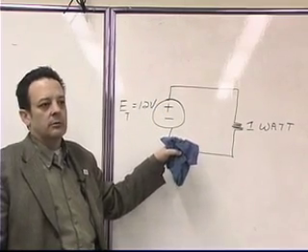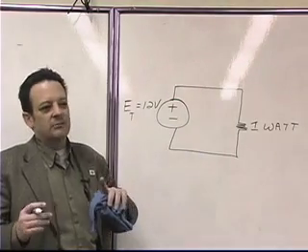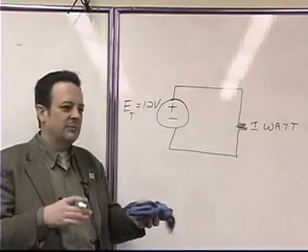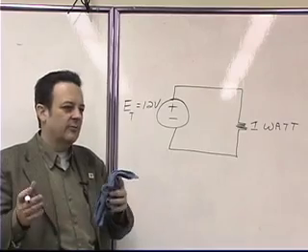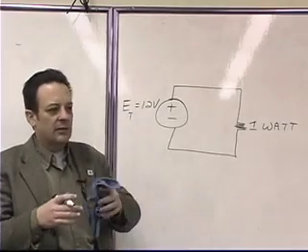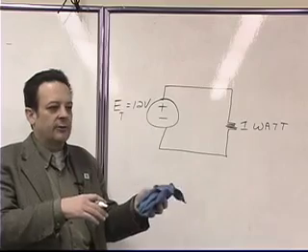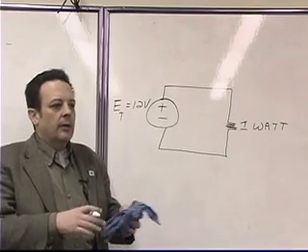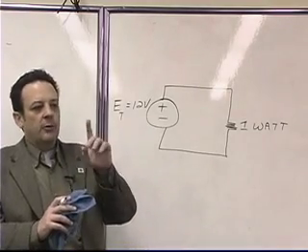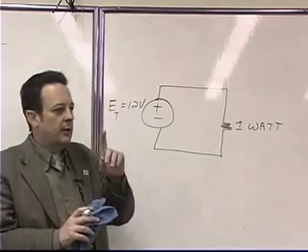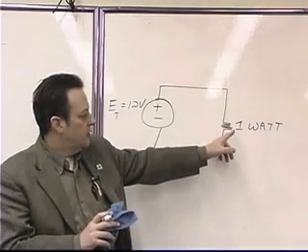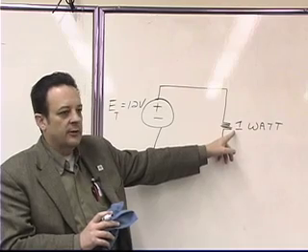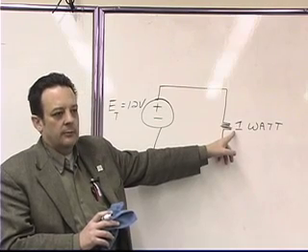Okay? If we expect that resistor to dissipate 1 watt, and we want to make sure that this is a reliable circuit, in other words, it's not just a cheap circuit that it really doesn't matter if it fails, it's involved in something that can just sort of be thrown away and replaced at will, then the one thing that we're going to want to do is make sure that we select a value of resistance that is overrated.